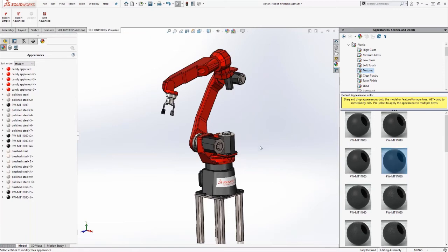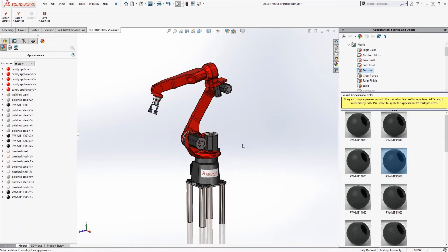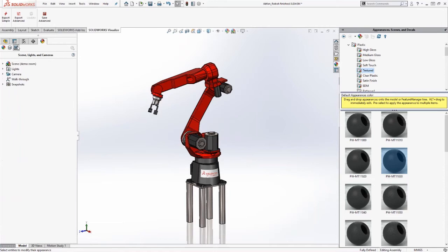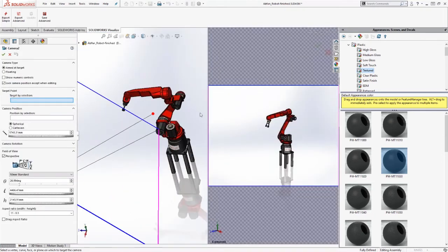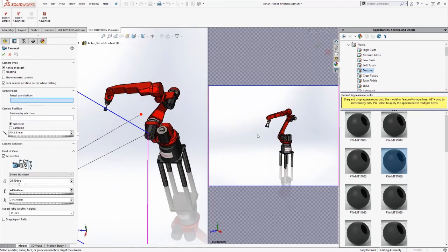Okay. Some other prep work, since we're kind of on the topic, some other prep work you can do in SolidWorks is you can set up camera views. It's nice to have a camera view set up so you can get that same exact camera angle again and reference it if you ever need to. Basically, if you click on this other tab in SolidWorks, the little cameras there, you can expand out. I already have one created, but say I add another one, I just click Add a Camera. Again, this is the same process you'd use for PhotoView 360, but the cameras do carry over to Visualize.